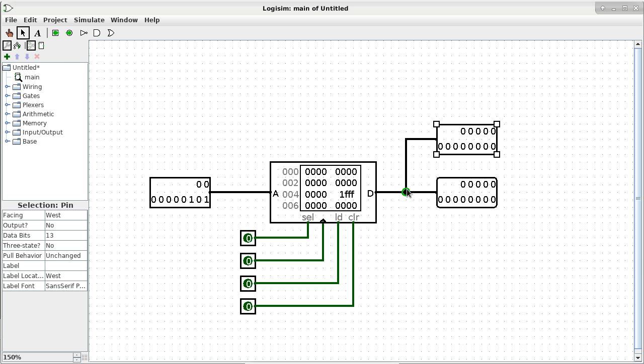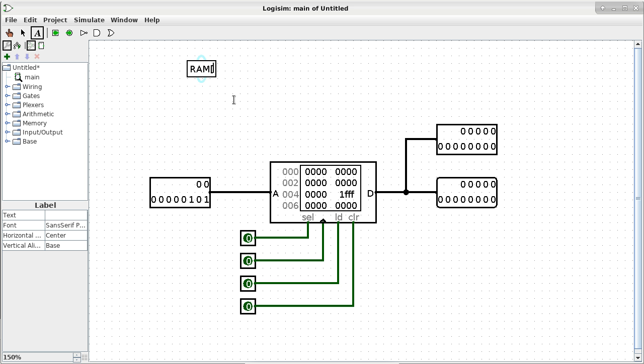Okay. So let's go ahead and try to overwrite some locations with a particular value. What I propose to do here is I'm going to use this kind of special notation, RAM, treat it as an array, and I'll just say that I want to change location 0x. Let's see, we got 3 bits, so it can go all the way up to 7. So let's say 53D. And I want to change the content at that location to... oh, I don't have that many bits, sorry. Because I only got 10 bits, so that means I have 2.5 digits. I can do 2F4, okay? So 2F4 is the location I want to change in hexadecimal.